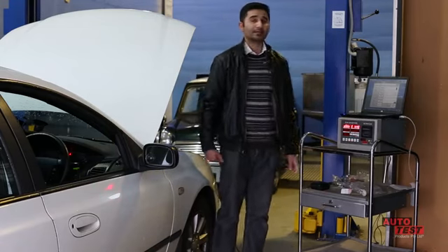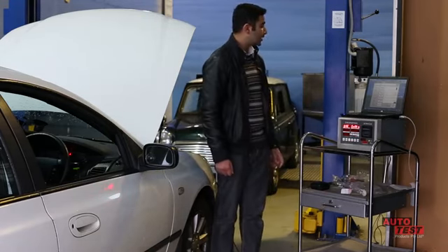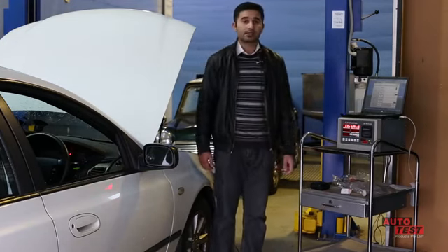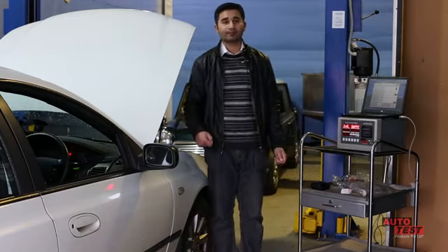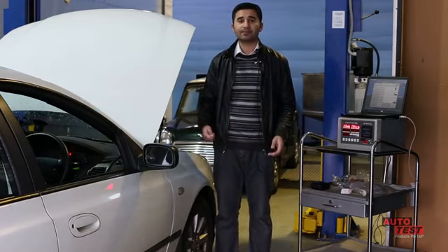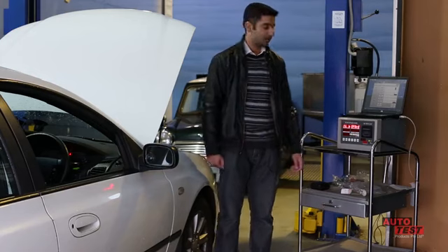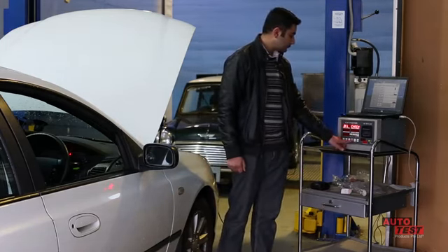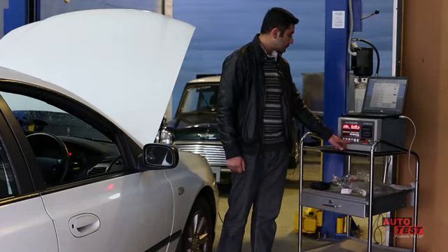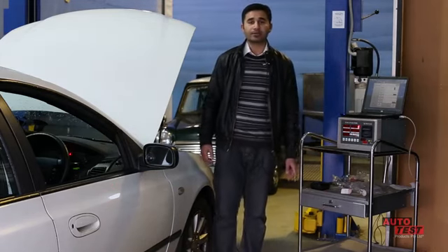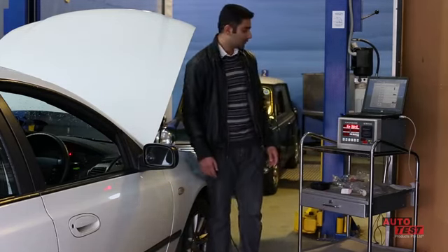Now the machine says ensure the engine contains sufficient oil before proceeding. So in this test, you have to make sure that the engine has enough oil, and that can be checked using the oil dipstick. The next step says run engine. Since the engine is already running, we don't need to do anything.